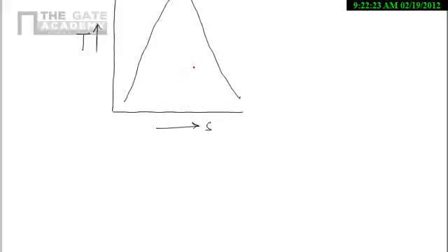Here we are having the state 1 and from 1 to 2 we are compressing, that is isentropic compression from 1 to 2. 2 to 3 will be in the condenser. If you see, 2 is a saturated vapor state, 3 is a saturated liquid state and again from 3 to 4 it is expanding in an expansion device and we are getting point 4 here.